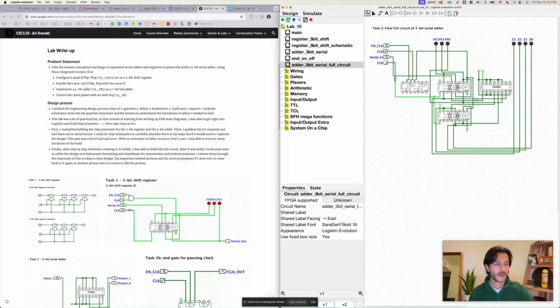So we have our various grounds that aren't used for certain inputs, and off we go. One little thing that I did differently is on this clear, I put this NOT gate because I didn't like having a clear active low where you had to turn it on to 1 so it wouldn't clear everything. So I cheated a bit here and added this. You can also add the associated NOT gate IC for it if you wanted to, but I just put the NOT gate on this one thing because that's all we needed.